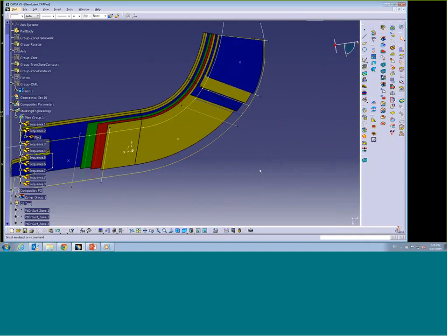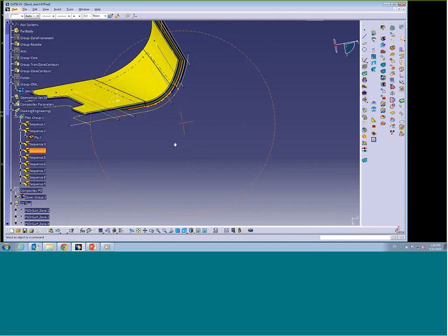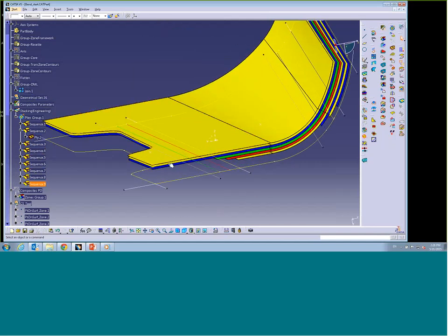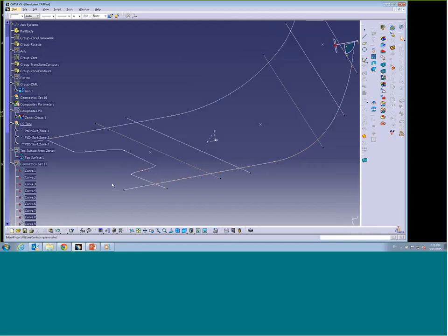So instead, what you're going to have to do is to actually create the stack-up file prior to creating plies, and in that stack-up file we're going to resequence the plies. So what I don't like is with this one, I have, as you see, 2 plies with 0-degree orientation at the very top. Not a very good idea.